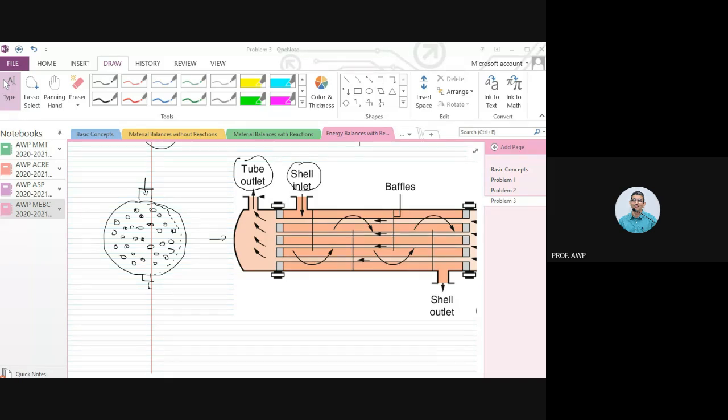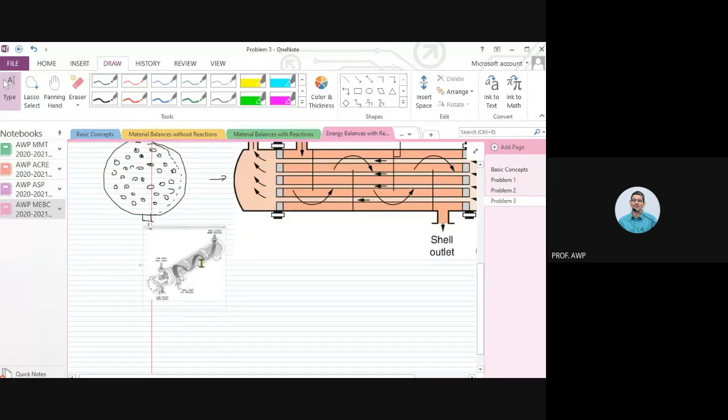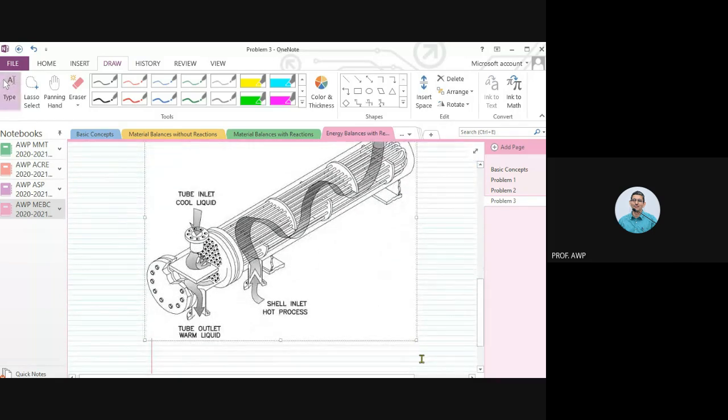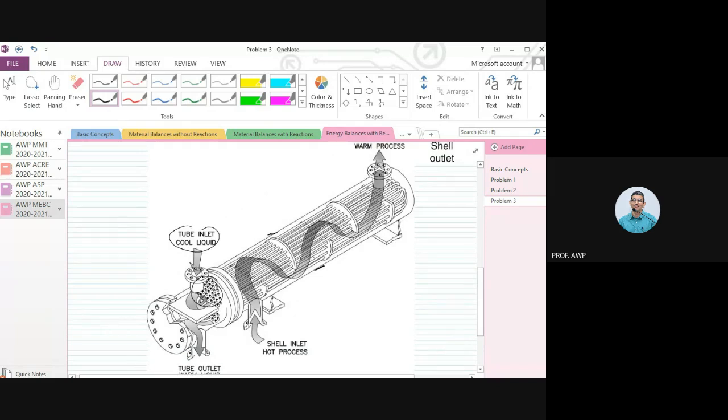It shows a 3D kind of view. Are you able to see? So you see these are the tubes. This is the outside shell, an isometric kind of view. These are all tubes you can see. The tube side gas comes in, goes through this top set of tubes, goes through these bends, and comes out from this end through this outlet. And the shell side comes here, goes in a zigzag manner, and comes out outside.